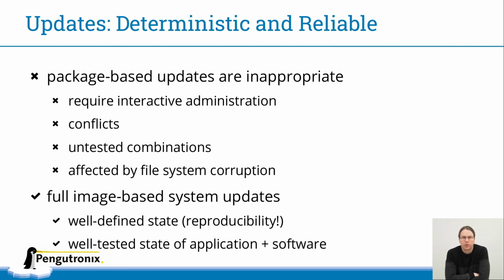You get untested combinations in the field, and it's also easier to affect that by file system corruption, because you usually have a writable file system underlying that. So instead, we use full image-based system updates, where you have basically the whole state of the system in a well-defined way in the update, and that is rolled out into the field, and then you can be sure that what you have tested is actually ending up on the devices.